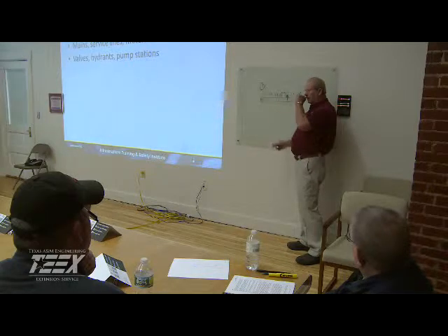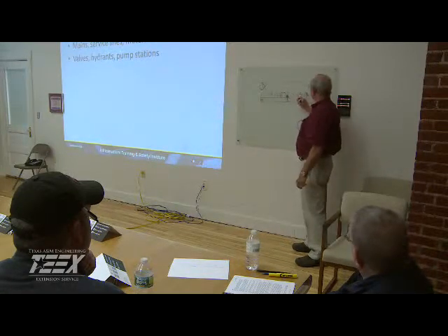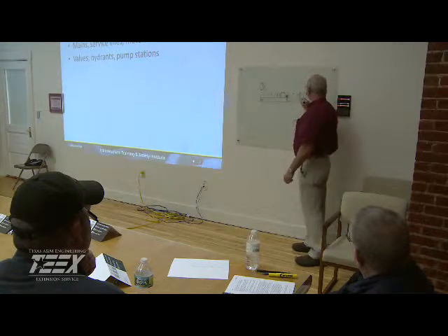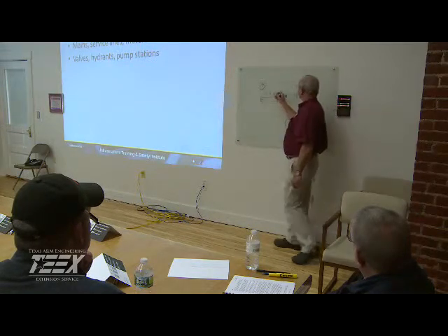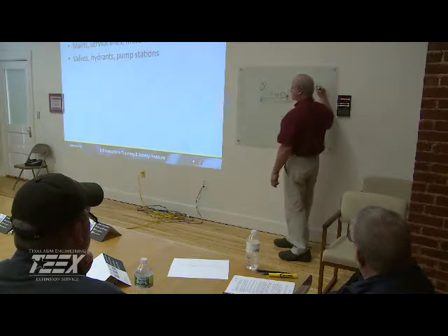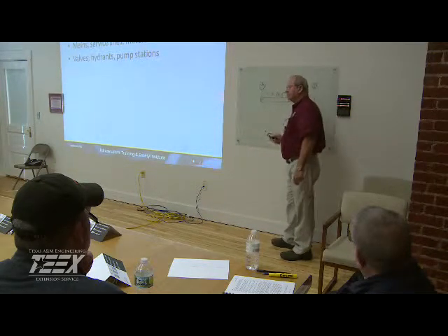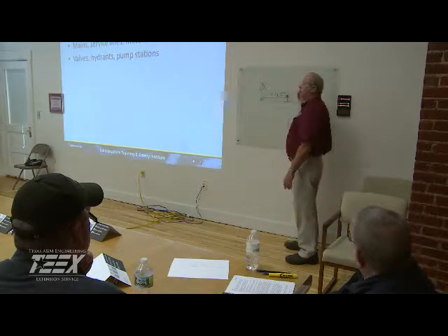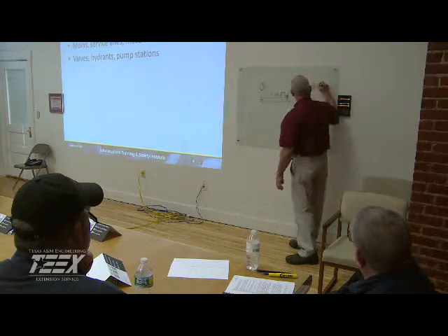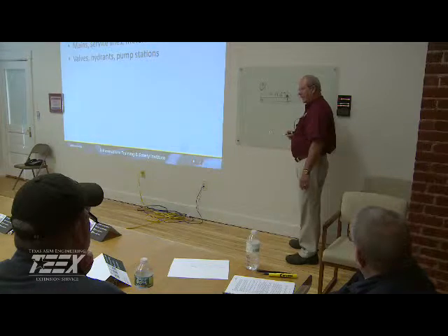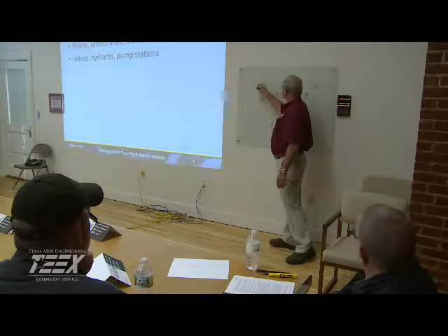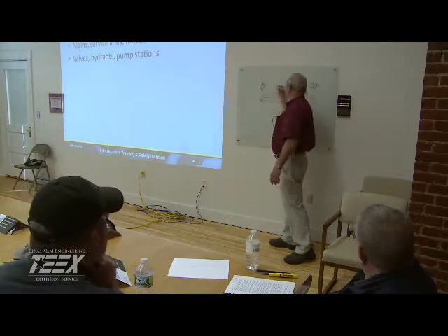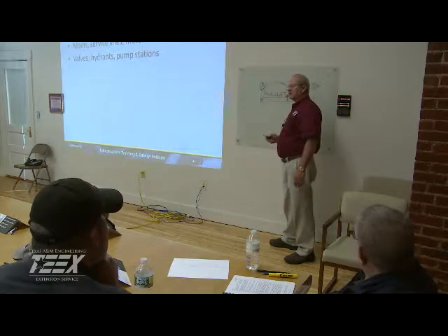Okay? Now, vice versa. As the fire department finishes fighting the fire and they turn off the fire hydrant, this tank is going to start to fill. Okay? Now, there's going to be what? A gradual filling of this tank. Water's still going into this tank. But at a given point, they're going to equalize. And then all of a sudden, the pressure is going to start dropping. And when the pressure drops, this valve will recognize that pressure drop and start to open, allow more water to come in here to maintain the pressure on this side of town. Make sense? Okay, so that's an altitude valve.